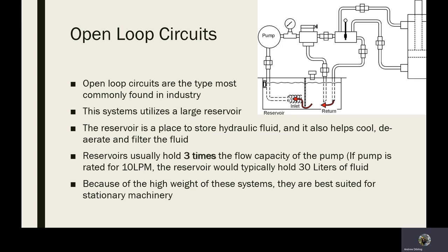Okay, so an open loop circuit is pretty much the standard for any equipment that is set in place. Open loop circuits are most commonly found in industry. They have a large reservoir, and this reservoir, as I mentioned before, has 3 times the fluid that you will find at any given time in the system. So really there's 3 parts of the fluid are in the reservoir cooling down and having impurities removed by settling and by these baffles and inlet filters.